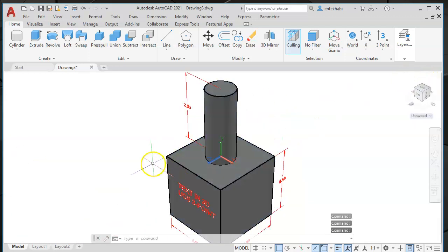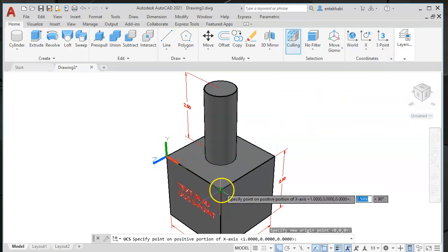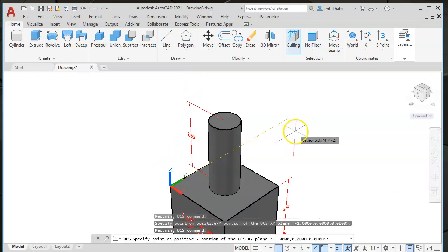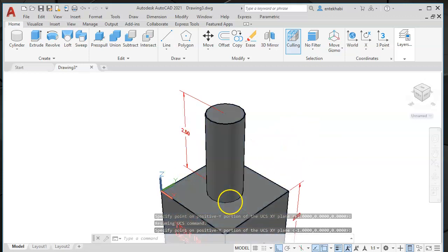Now, adding the location for this, I need to be on this plane. I can do that by face option, or as shows on your assignment sheet, I have in this corner. Either way it should work. I'm going to use the 3 points, selecting the point 1, point 2 for the X, and having this point for Y. As you notice that XY is parallel to this face.